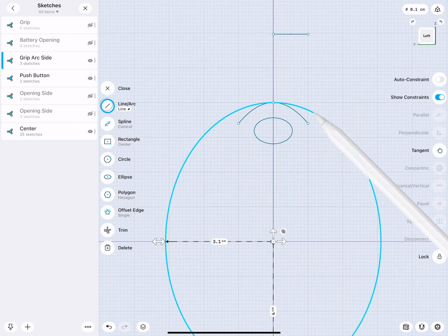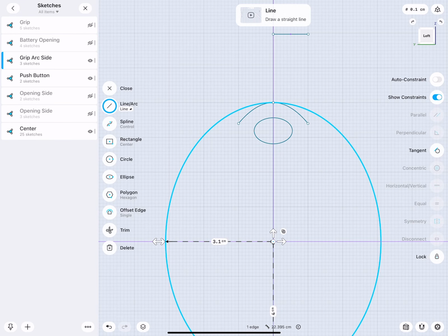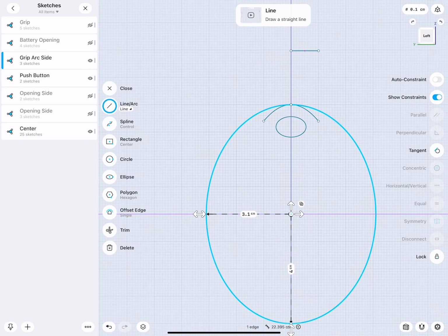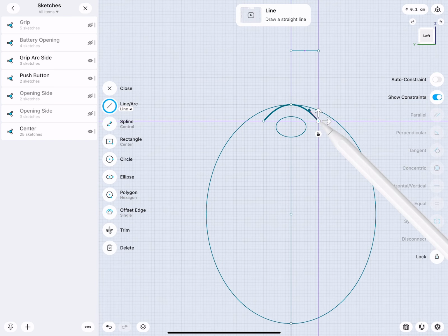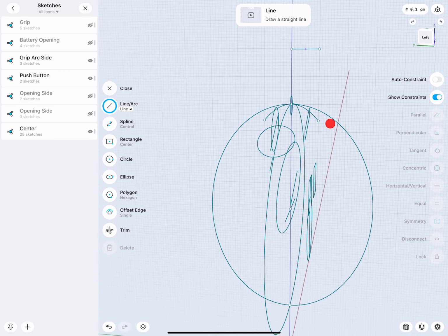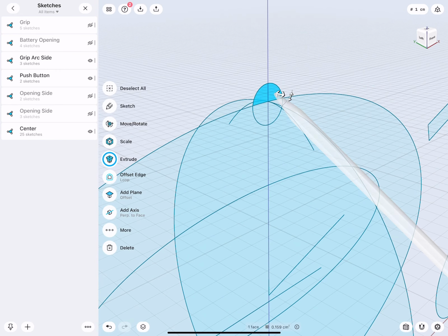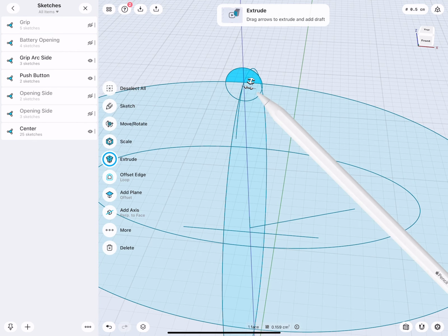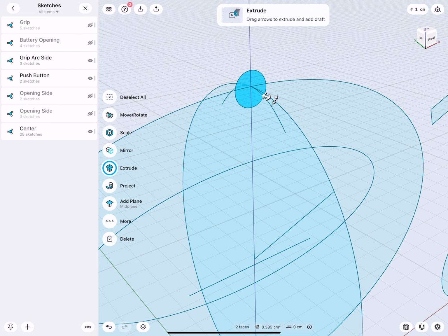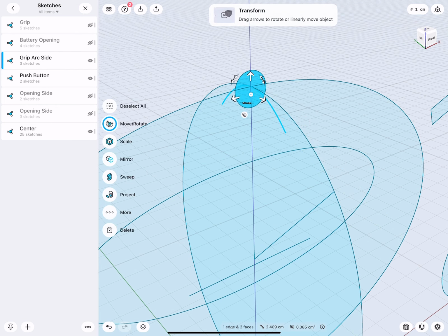So in this view, now this is the desired outline of the massage tool. And here you see the endpoints are inside and they go down. And all we need to do is select half. If we want, we can select both. Select the arc and then select sweep.